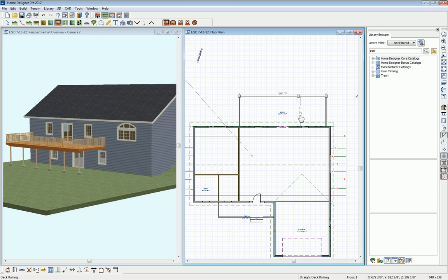Now let's change the dimension. Single click on that railing and then single click on the temporary dimension, and let's change that to 10 feet. We can also alter that railing. It's still selected. So let's go down to our editing toolbar at the bottom, and we can change this to have an arc to it. So we can curve things pretty easily with that change line to arc tool. So that's pretty good as well if you didn't use our curved deck tool already.